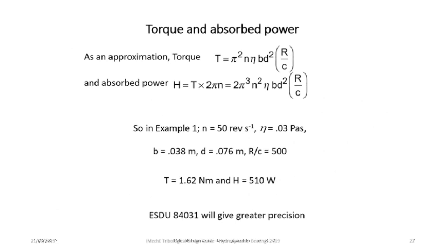It's always useful to have an idea of how much torque the bearing is absorbing, and thus how much energy is being expended in shearing the oil film. The Petrov equation can provide a quick estimate. This is based on the idea that the fluid film fully occupies the gap between the journal and the bearing, but that the shaft is running concentrically.